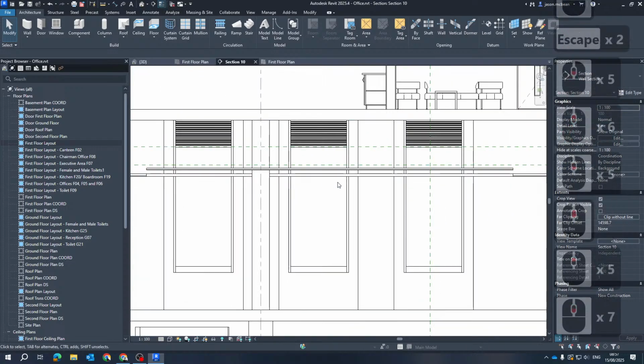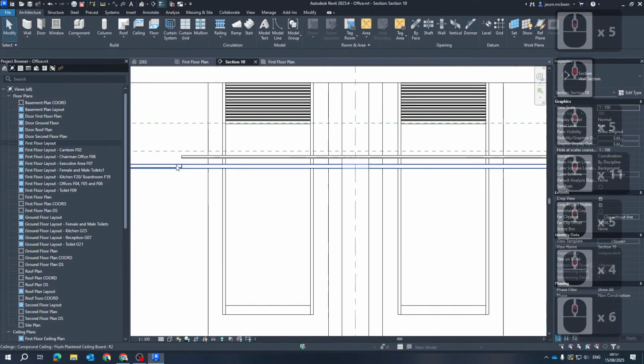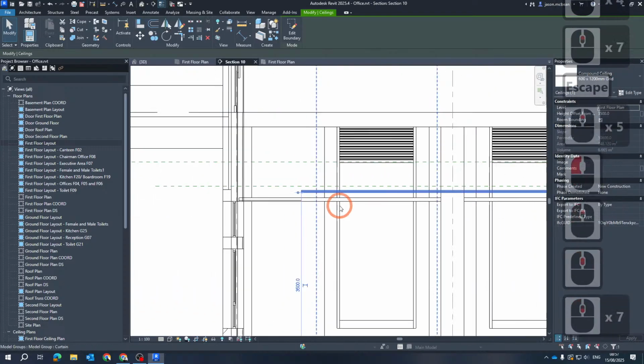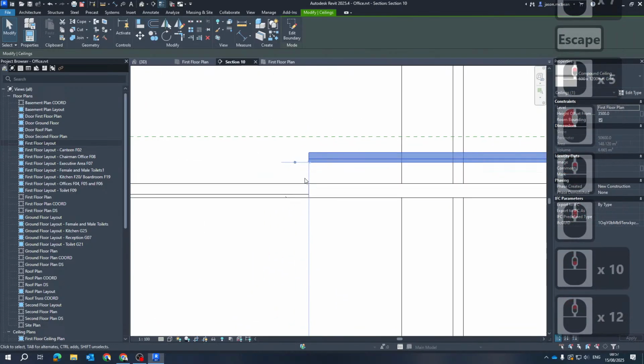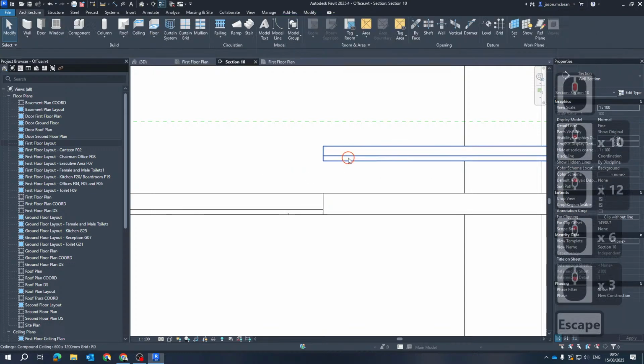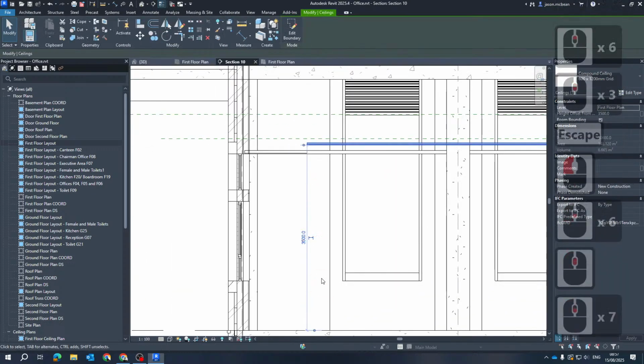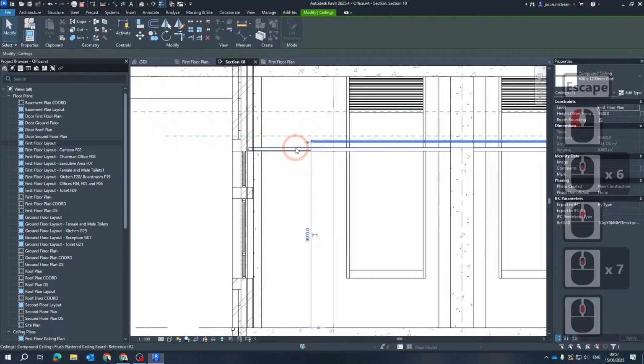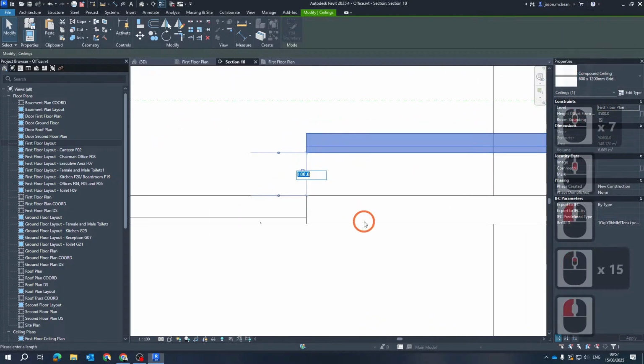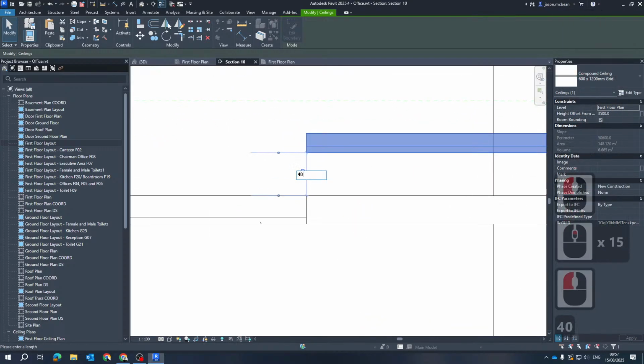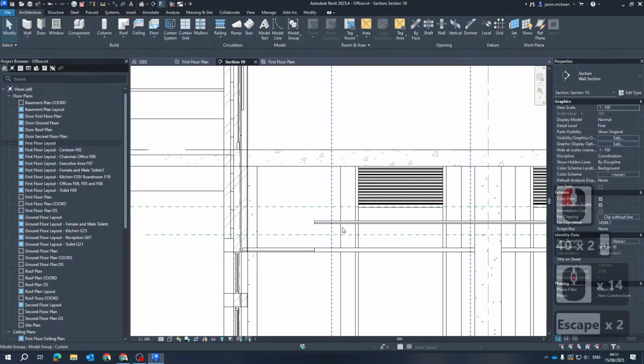And you see that the window heights in the back, they all conform to that standard. What I might want to do with this office ceiling for the light, I might want to create some like a ring of light, and I might want to move this up a fraction just so I've got enough play above this ceiling. Okay, so let's make that 400. So there's a nice little upstand here. Then we've got our ceiling grid.